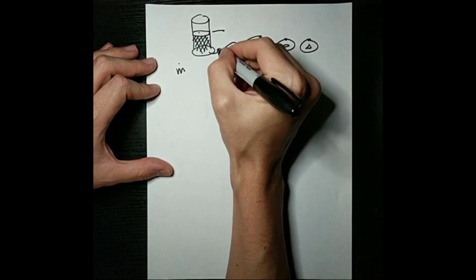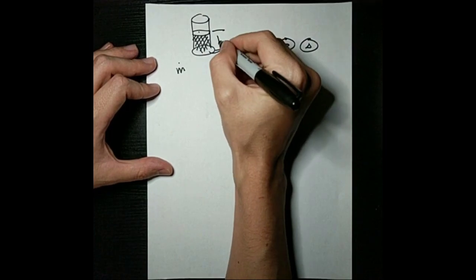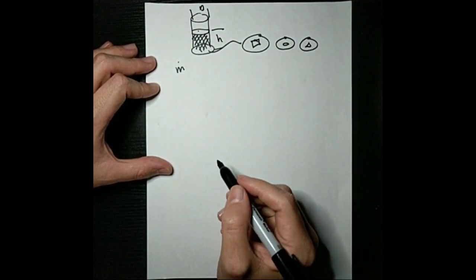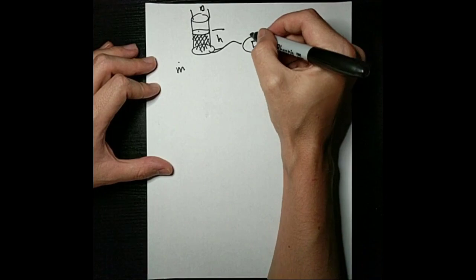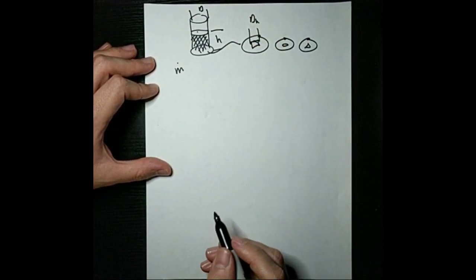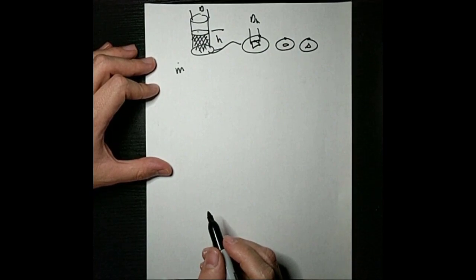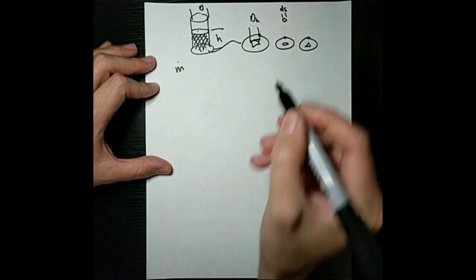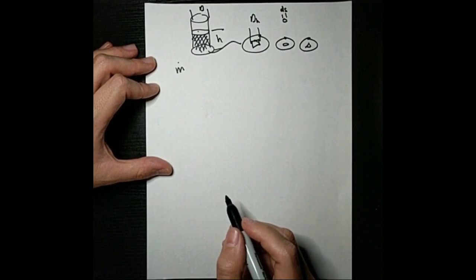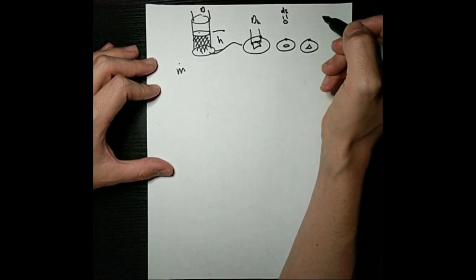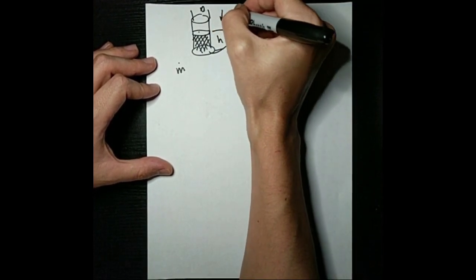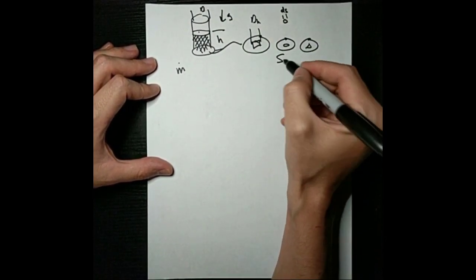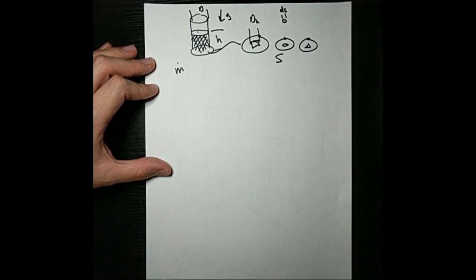So we'd also maybe consider the height that we're packing the material into, the diameter of the column that we're filling, the hydraulic diameter of the orifice, the individual size of the particles, which we're going to be assuming are spherical, their bulk density, their true density, the gravity force, that'll be the main force causing the flow, and then there'll be some shape factor that will affect it.